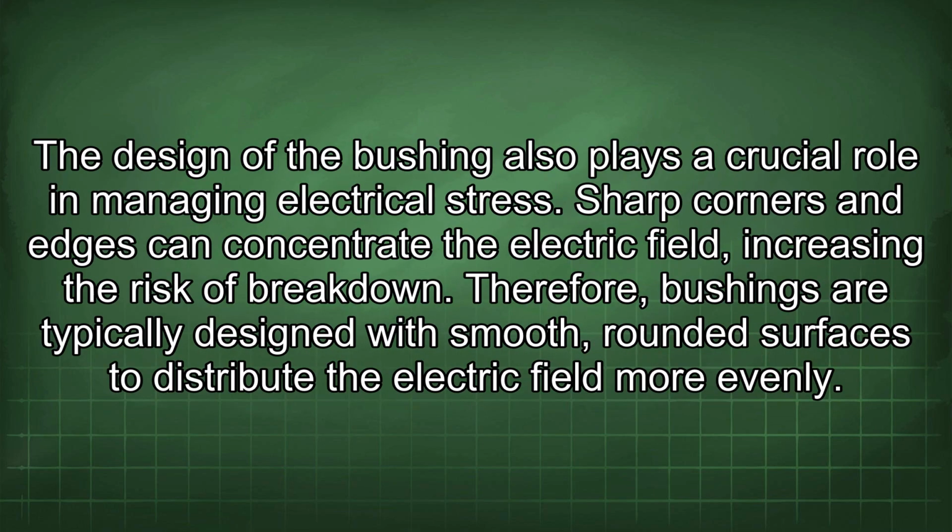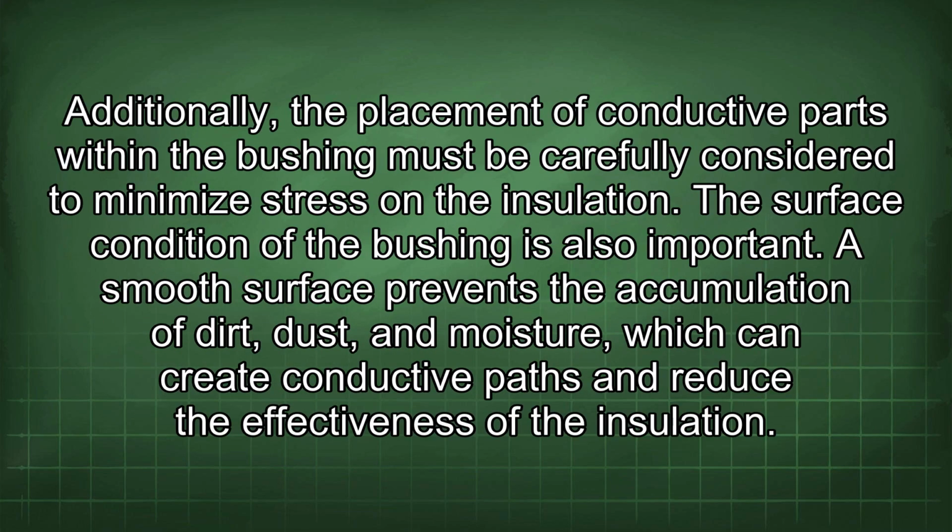The design of the bushing also plays a crucial role in managing electrical stress. Sharp corners and edges can concentrate the electric field, increasing the risk of breakdown. Therefore, bushings are typically designed with smooth, rounded surfaces to distribute the electric field more evenly. Additionally, the placement of conductive parts within the bushing must be carefully considered to minimize stress on the insulation.